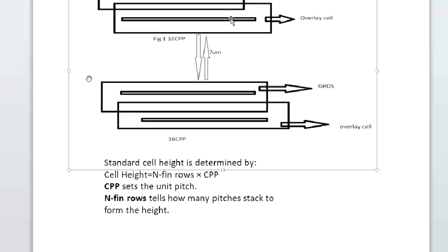How does the overlay cell help in power delivery? The overlay cell has a wide density of metal straps and via redundancy. Through that, it has pins like VDD, VSS, VDD AON, and VDD power switch. So these are the pin names in the design.